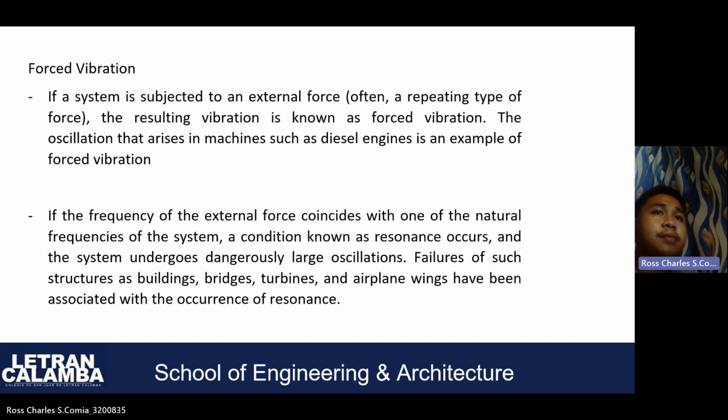Examples of these types of vibration include the washing machine shaking due to imbalance, transportation vibration caused by an engine or an uneven road, or the vibration of a building during an earthquake. For linear systems, the frequency of the steady-state vibration response resulting from the application of a periodic harmonic input is equal to the frequency of the applied force or motion, with the response magnitude being dependent on the actual mechanical system.